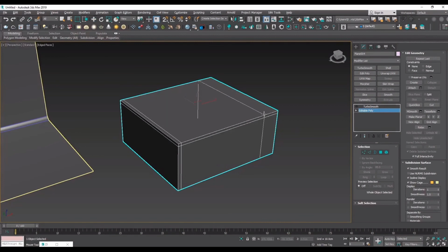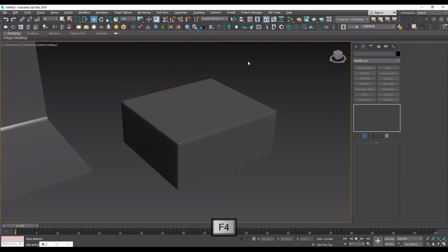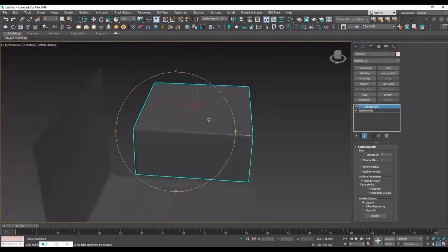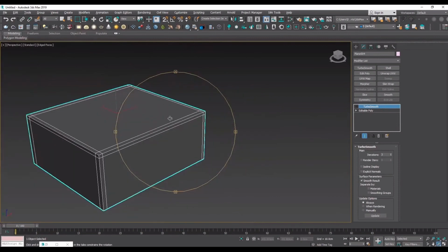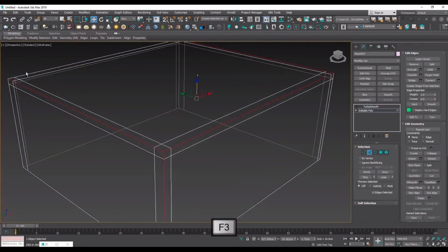Just like before, this is now the second model we had earlier. When we got the fillet effect, we can get chamfer effect again by dissolving the edges between, by clicking on the edge twice, and then add the supportive edges to our main defining shape to preserve the chamfer effect. This way, Turbo Smooth sees nothing extra to make the curve out of. I dissolve this by pressing Ctrl and hit Delete.